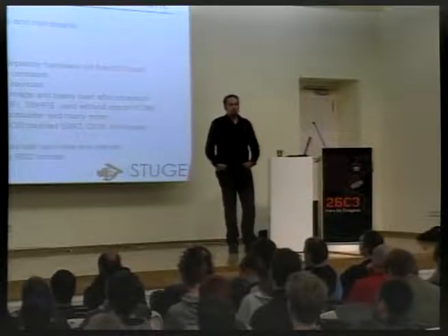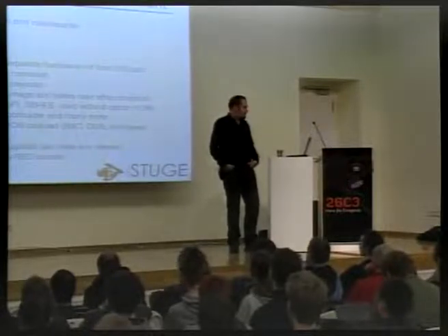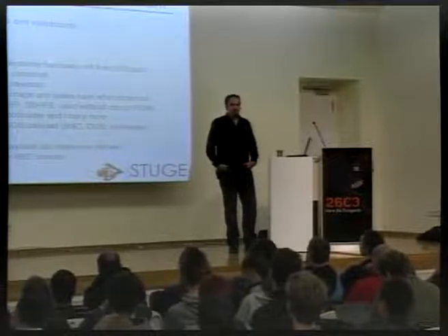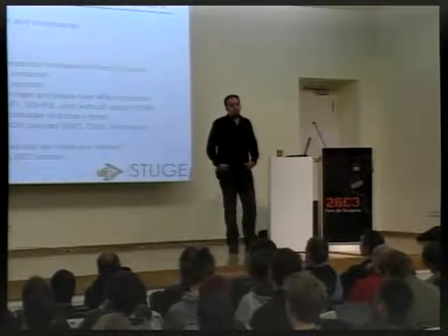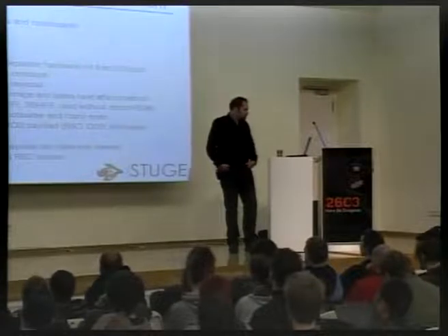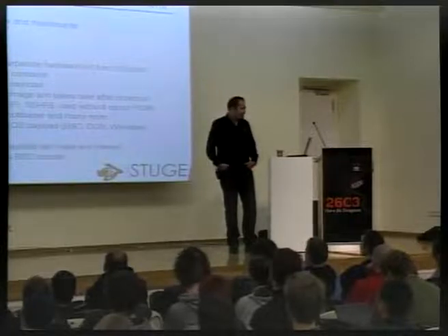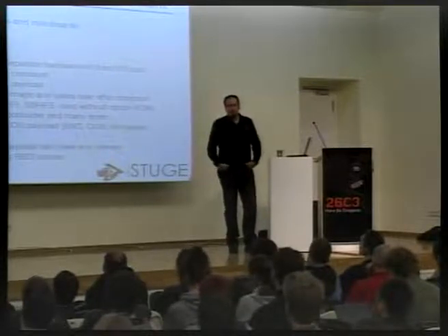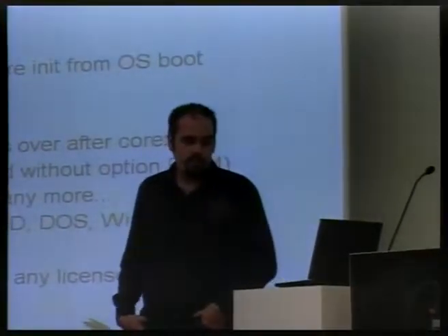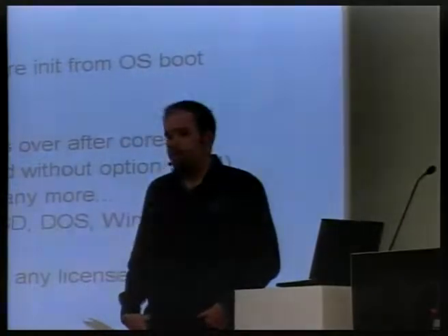I think it's important to remember that coreboot is not just an open source BIOS. It's not a standard BIOS. It brings a new concept. It separates the hardware initialization from the operating system load. And the traditional BIOS will do both of these. Coreboot does just the hardware initialization, and it's new code, so legacy-free, no assembly, 32-bit mode. And the bootloader is isolated into its own program called a payload. The payload goes into the ROM image together with coreboot, and when coreboot is done running, it jumps to the payload, and the payload can't really jump back.